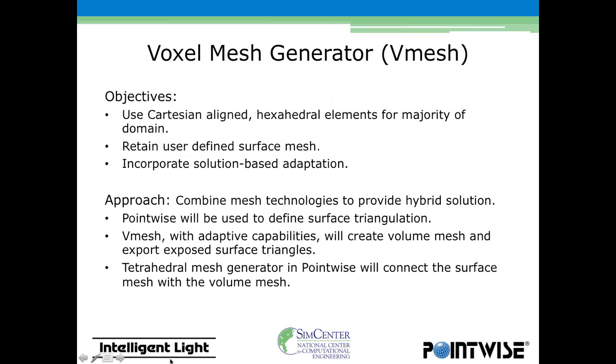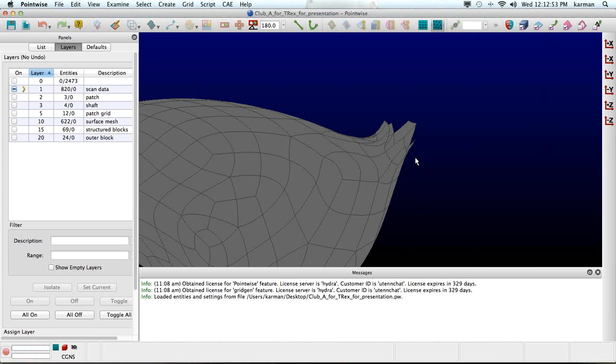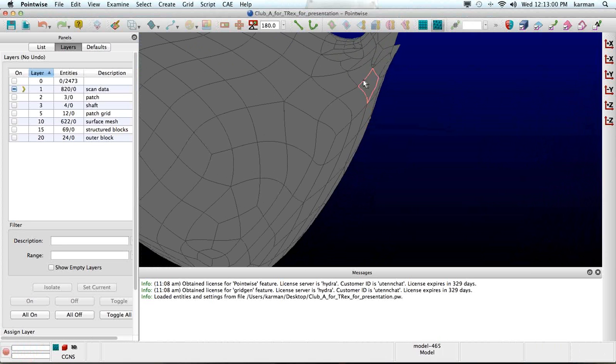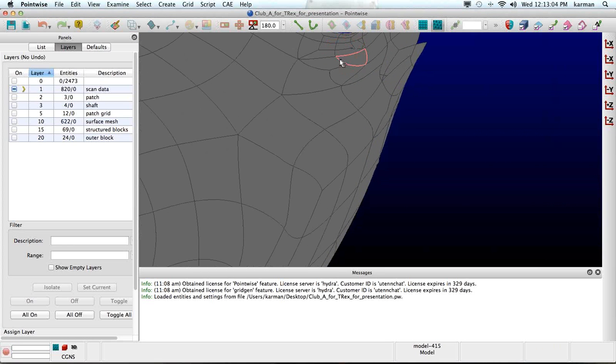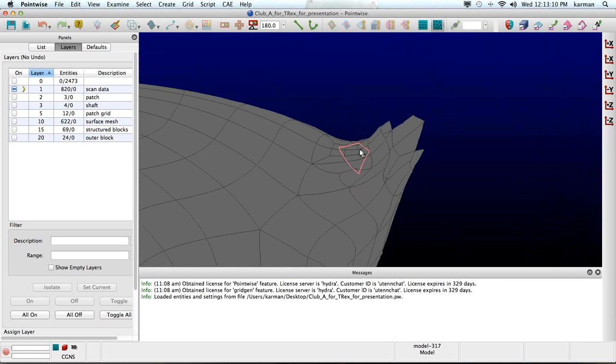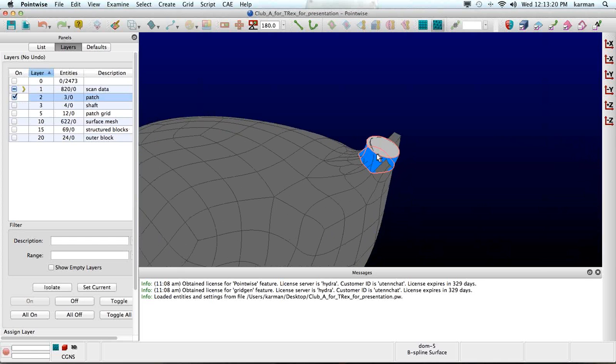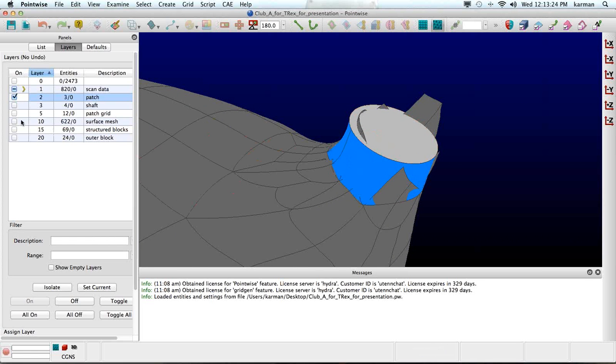So let me pull over to Pointwise very quickly and show you in a little more detail what I'm talking about. You can see that right here in the golf club surface itself, there were lots of anomalies. And this was after extensive cleanup in the pre-processing of the laser scan. So all I had to do was make a nice little patch, and that was accomplished with actually a structured mesh, which are fairly simple to turn into database elements, into geometry itself.